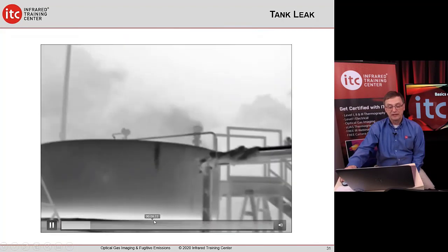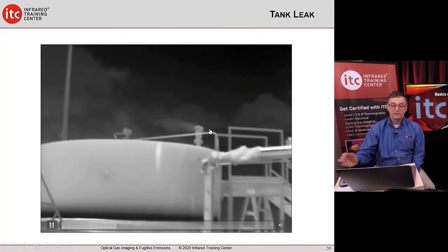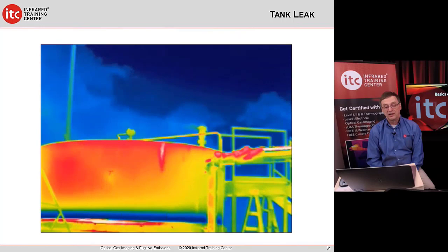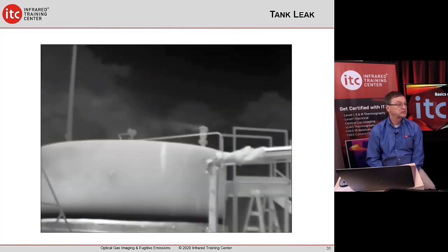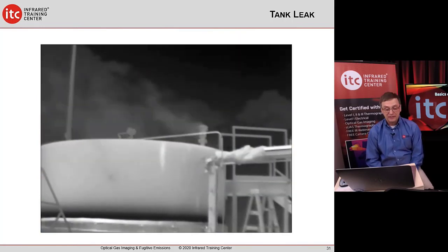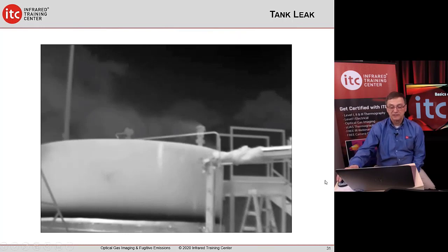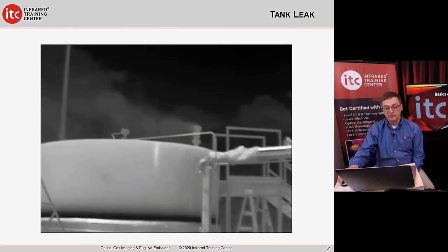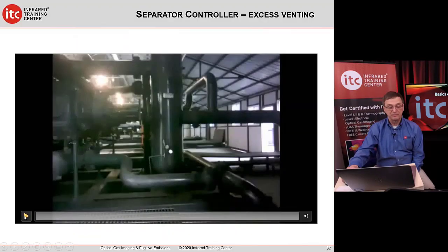You see the bottom right there, but it had a pressure relief valve, an Enardo valve, which is both a vacuum breaker and a pressure relief valve that was leaking. And obviously a very windy day, this was a substantial leak. And this was found as part of our training class. They got it repaired, I think it was repaired by the end of the day, if I remember right. And so it was the first time the yard had been inspected.